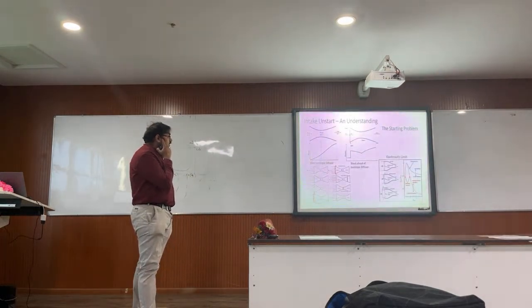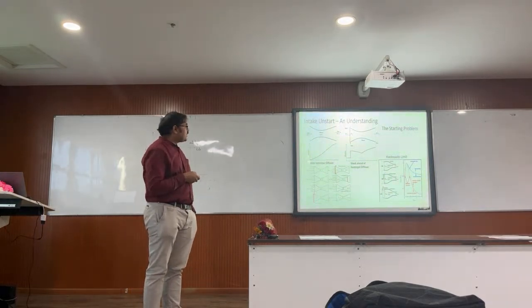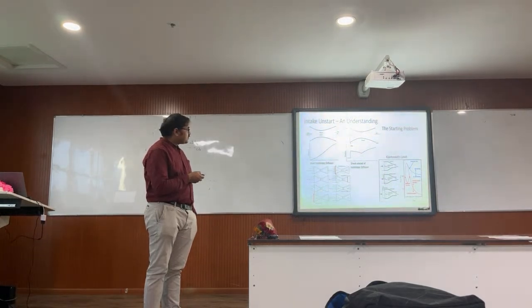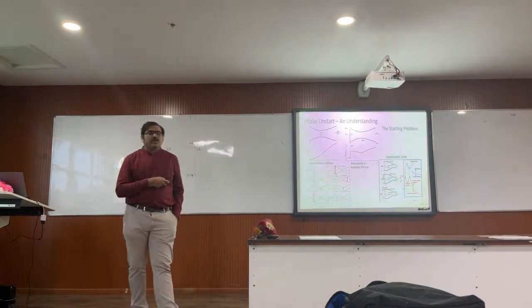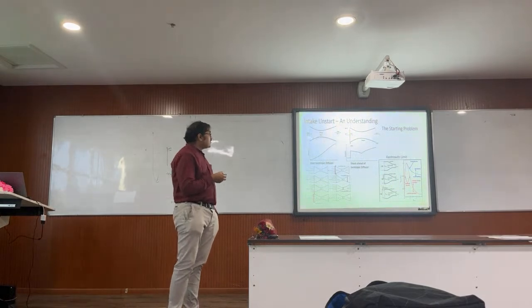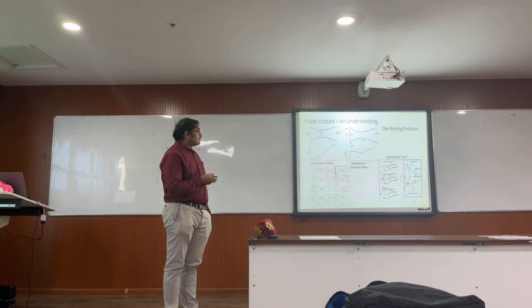Okay, so if you consider an ideal diffuser, this is an ideal supersonic diffuser, and it's completely isentropic. There are no shocks. Then, if it is going to convert a supersonic flow into a subsonic flow, then we have a minimum area, and we expect that the minimum area will contain Mach number 1. Okay, and this is the choking phenomenon in varying area ducts of supersonic flows.